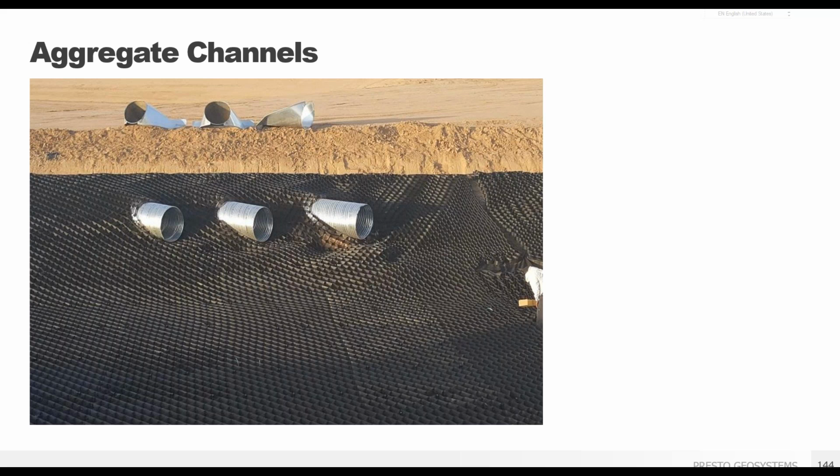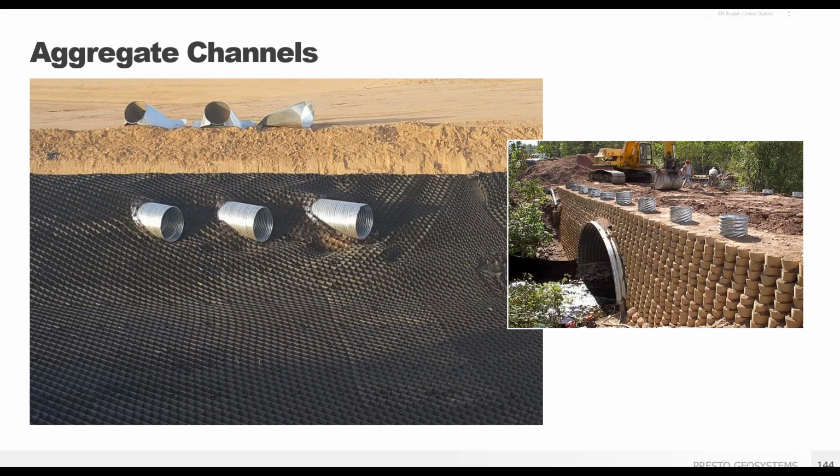The GeoWeb panels are very flexible and can be easily cut in the field to allow for pipe penetrations, as we saw with the sonotubes in the GeoWeb wall portion. And again, no loss of integrity with the system performance. Here we see some drainage pipes from a nearby detention pond. It's very simple to complete field cuts of the GeoWeb panels and accommodate structures like these, so there are no areas left unprotected. The area right below the drainage weirs should be built more robustly, since this is the area with the highest potential for stone washout due to turbulence of water coming out of the pipes.